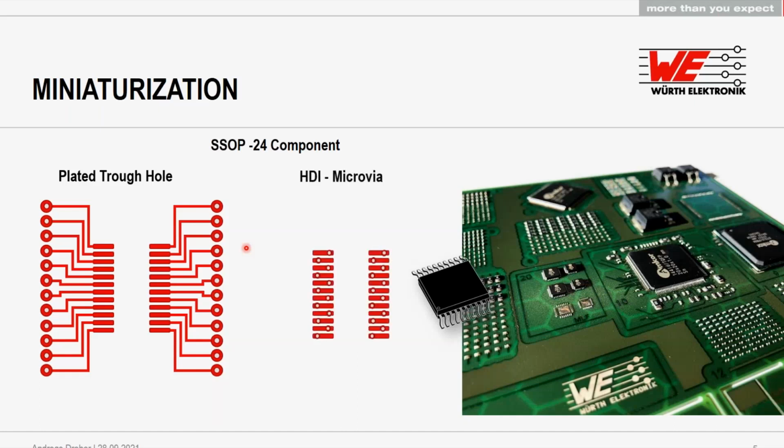A good alternative is to use microvias. Microvias are laser drilled holes, typically from just one layer to the next layer. The diameter is smaller, maybe 150 microns, so the land diameter of a pad can also be smaller. In this case, the microvia pads are 300 microns, which is exactly the same size as the component soldering pad, so they fit directly into it.